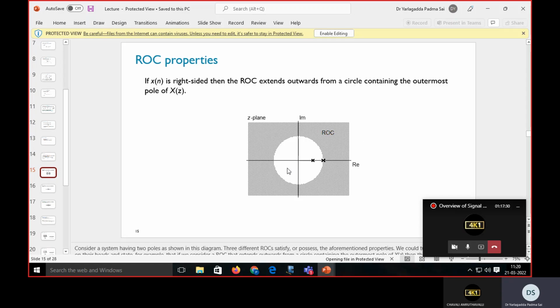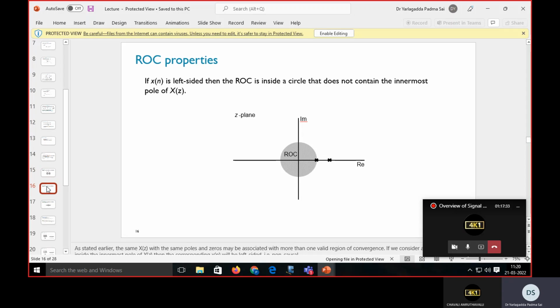Okay, so already I mentioned this one. ROC is explaining how actually the same concept we are using in IIR filters also. Mainly we are designing a Butterworth filter, and we are transforming all the poles according to Laplace. The poles which are lying on the left half of S are stable. Okay, we have to map all the poles lying on the left into the unit circle.